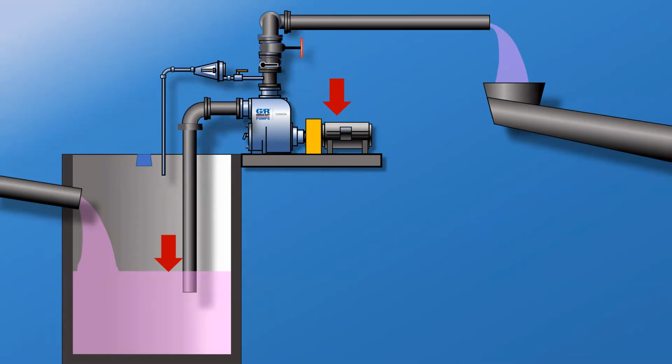Yeah, so if we went back to that just on-off control without the level transducer, if we're just operating off of floats and we have an active well, we might also run into issues with cycling the motor too much. I'm sure most people know we're not supposed to turn a motor on and off 20 times an hour. And again, without a soft starter or a VFD, you'll burn out that motor if we have an active pit and a wet well that's not too big, just because the motor will be turning on and off every 5-10 minutes. Okay, that makes a lot of sense. So it's a process and also equipment lifespan as well.